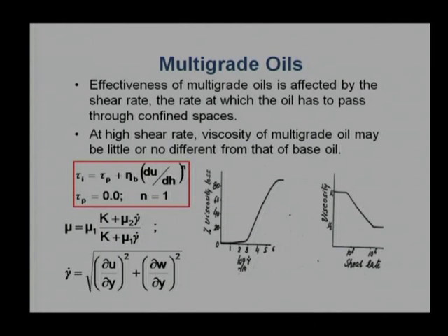It is more like an S-curve diagram. Initially there is no change, then suddenly a change, and after that it reaches a knee formation with a constant value, where the mineral oil is not dependent much on the shear rate. It works as a Newtonian fluid. In other words, mineral oil mixed with polymer additives can show two kinds of Newtonian fluids: a high viscosity Newtonian fluid initially at the low shear rate, and a low viscosity Newtonian fluid at the high shear rate, and the transition behavior in between can be obtained by using this relation.